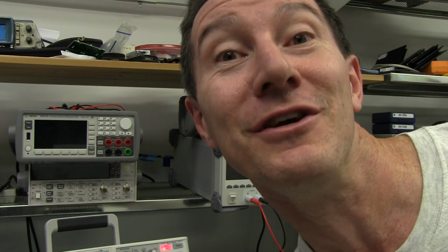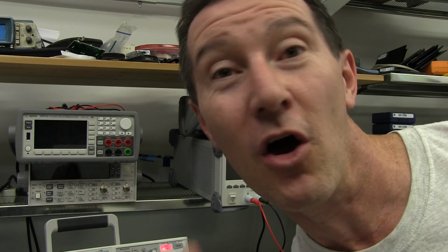These class 2 ceramic capacitors change their capacitance based on the applied DC bias level. Unbelievable. Who knew? They don't tell you that in the data sheets, the bastards. But not only that, the capacitance also changes with the applied AC voltage level as well, not just a DC bias offset.